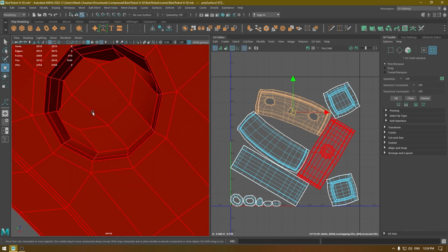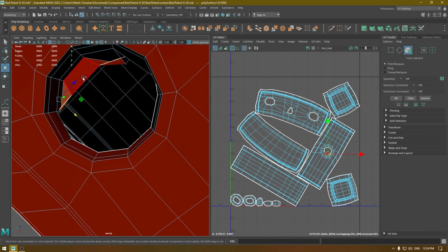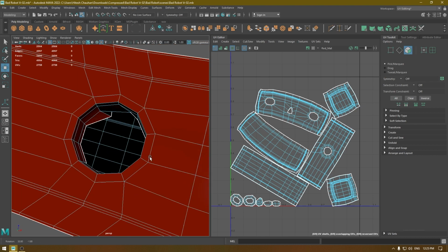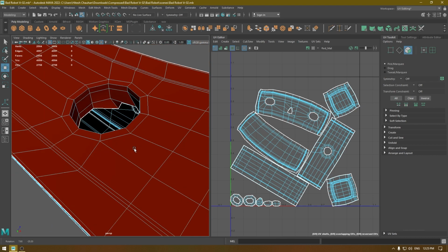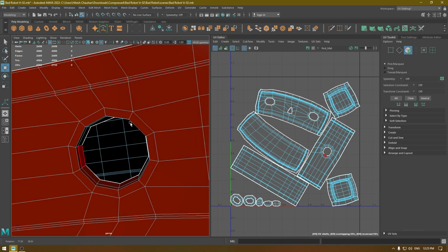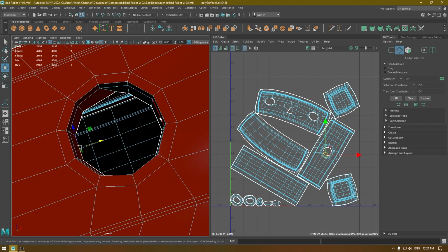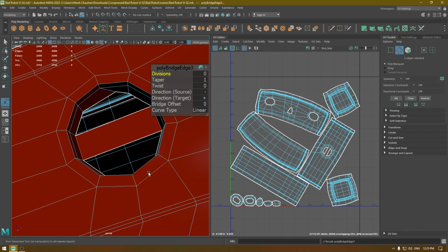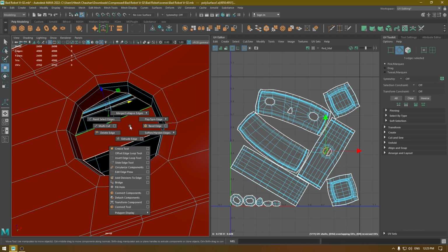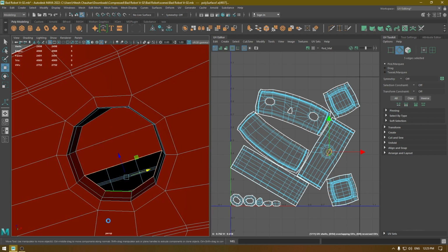And also we're going to fix this mesh. I'm going to delete all these faces. These don't look good. And now I'm just going to select this and this, then bridge, then select this and again fill hole. Repeat the same thing with this one.